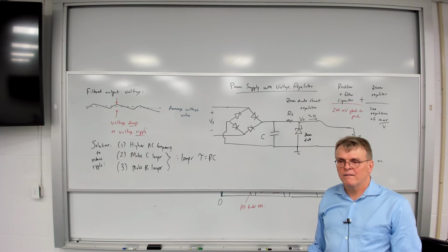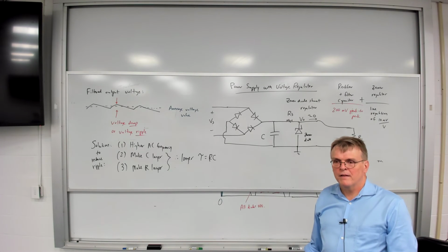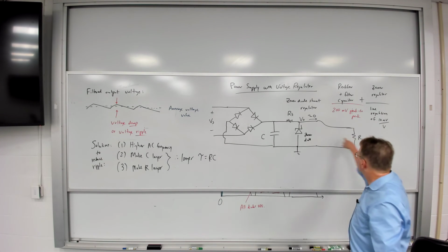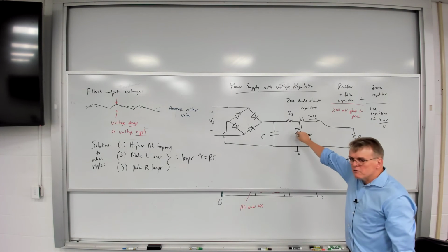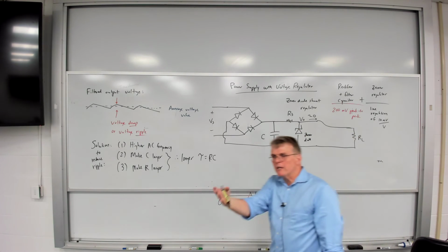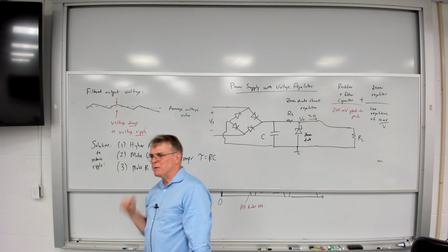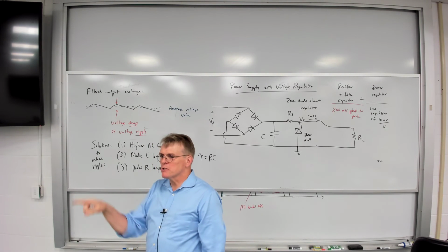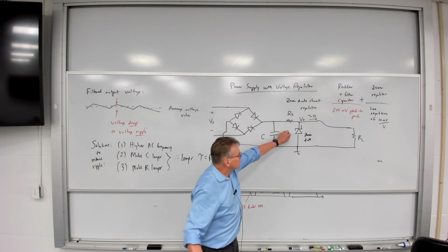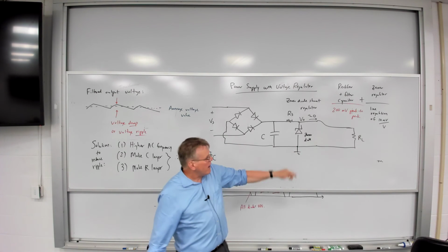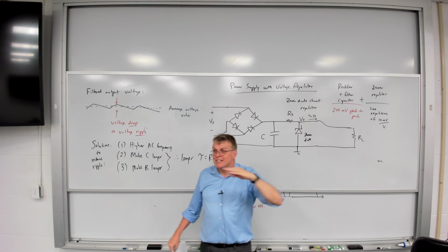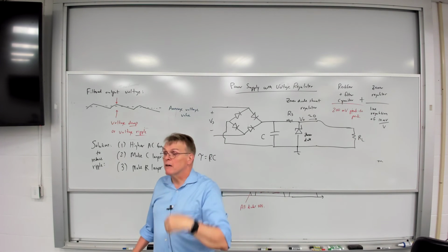So how does the op amp limit the voltage drop? Well, in this case, I have a loading effect. If I change the value of RL, the value of VO changes. That's load regulation. Remember, we talked about that last week, too. There's line regulation, there's load regulation. The voltage across the diode, VO, is going to change due to both. Adding the op amp reduces the loading effect, or improves the load regulation, I should say.